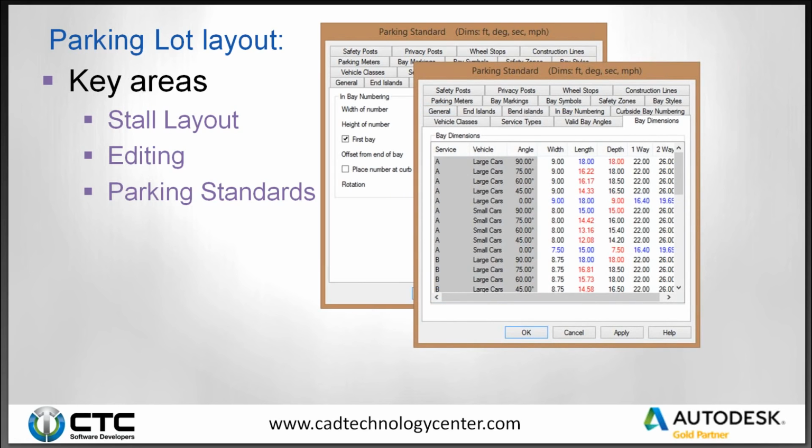The next one is the bay dimensions. Depending on if I have a large car with 90-degree parking, I have a width of 9 feet, length of 18 feet. But if it's 75 degrees, so it's like angle parking, my length is a little bit shorter. And then it gets shorter depending on how big the angle is. So you have the ability to make adjustments to these values. Maybe I want a large car and I want 10-foot widths, but I want 20-foot depth. We have a lot of oversized heavy-duty pickup trucks that are going to work towards this.